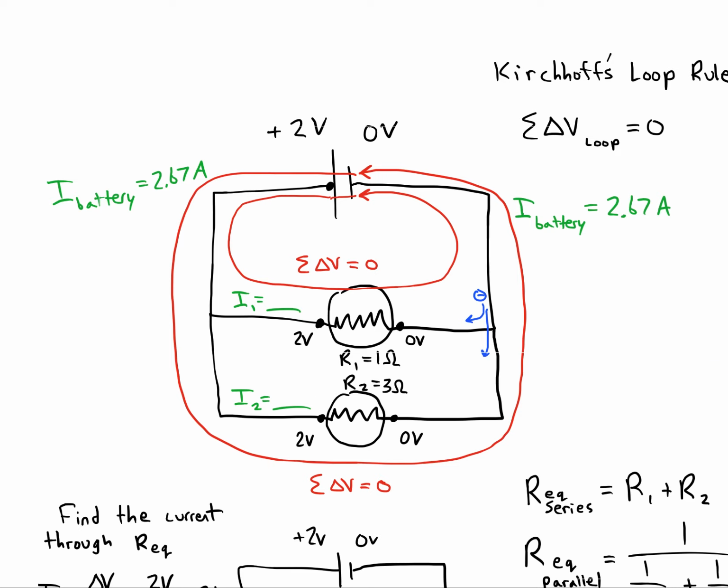The calculation that's required, I had actually already done. All it is we just want to apply Ohm's law to just this bulb alone now. All right, so that's easy to do. We'll find I1 by I1 equals delta V1 over R1, 2 volt drop, 1 ohm resistor, 2 amps.